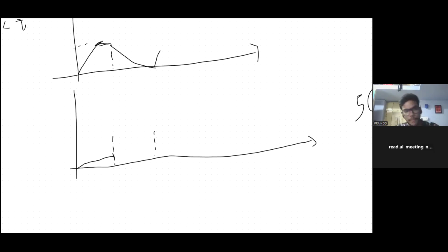At this point, for example, it has just charged up to 2 volt. So what is the current flowing? 5 minus 2, right? 3 by R. During discharging, it's flowing in the opposite direction. So it will discharge with 2 by R current, which is not equal to the charging current, right? So it will discharge to some value other than 0. The capacitor was thinking to reach zero, but it can't reach zero.